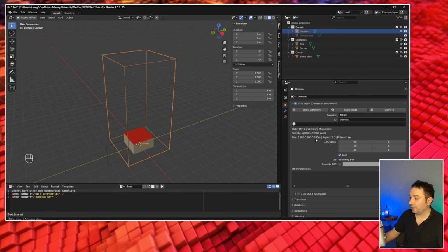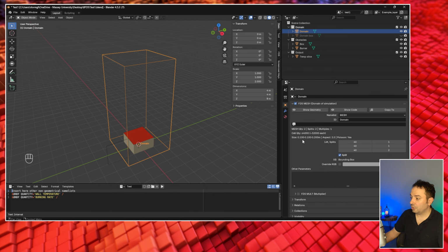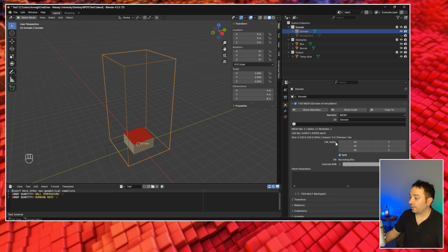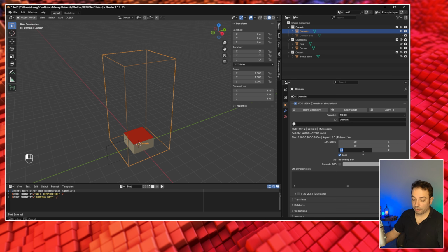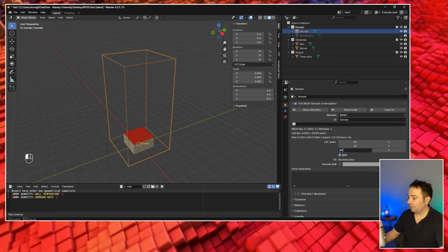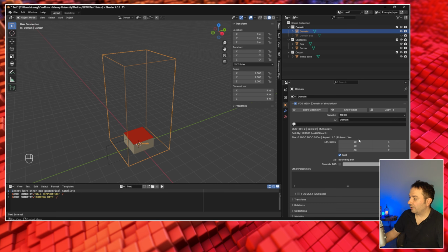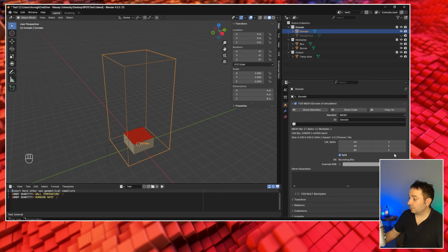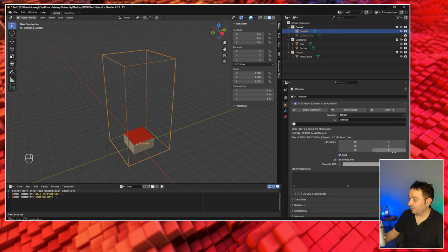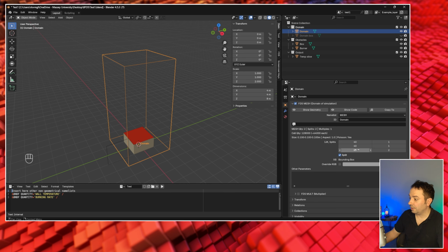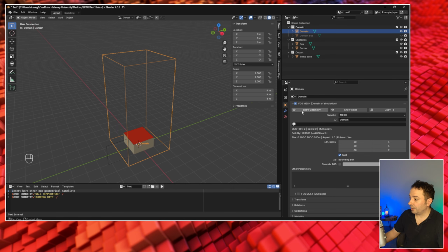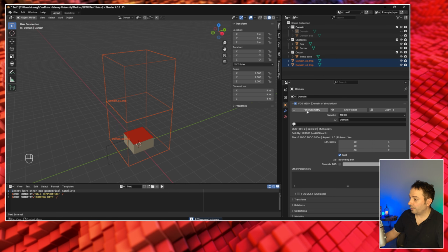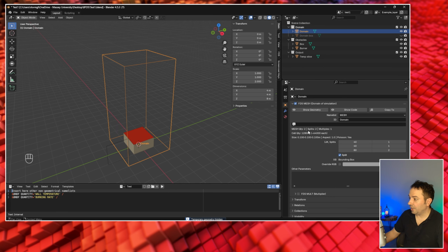In fact, you will see that now this mesh has cells that are 0.1, 0.1 and 0.2. So in this case, we need to reflect the change by also doubling the number of cells on the z-axis. If we want to show the two domains, in fact, you see here that the mesh is split in two, we can just show geometry and be happy with it.